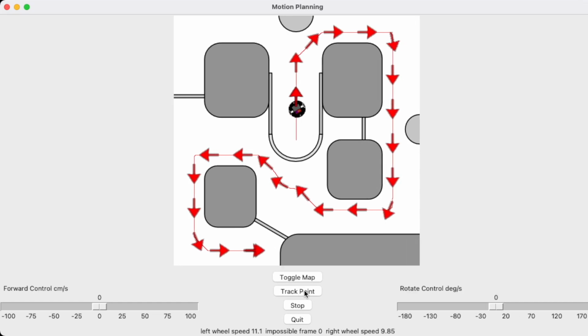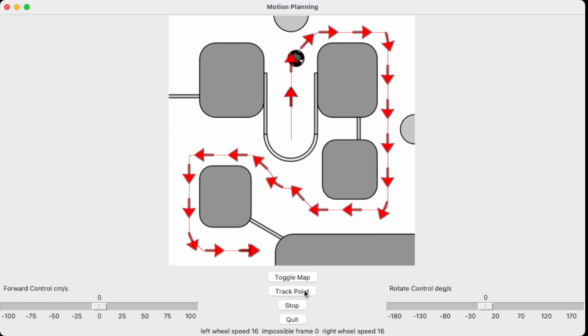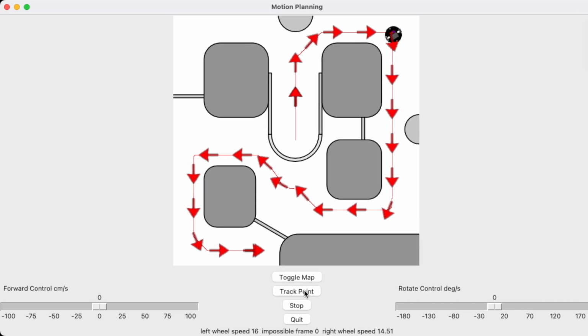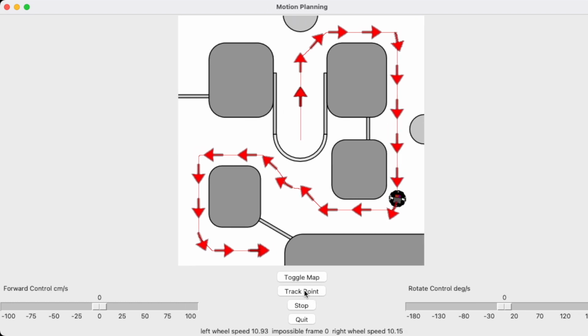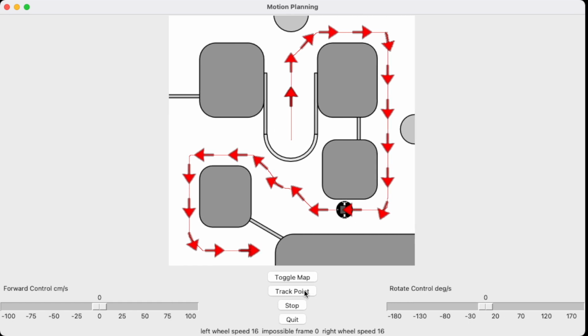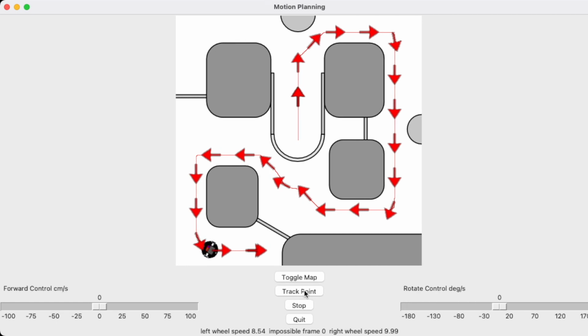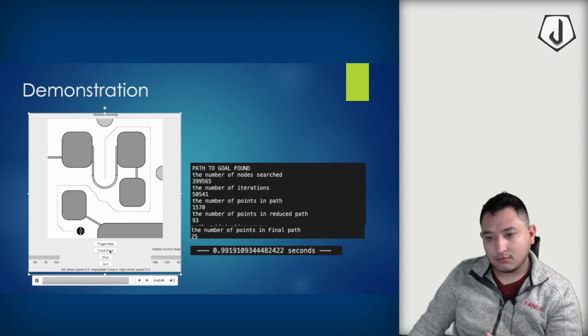As you can see, it moves very similar to a truck. It does not rotate in its place. It only takes curves along a maximum of 40 degrees steering angle. Its wheel velocity is limited to 20 rotations per second. As you can see, it will easily find its way from any starting position to any goal position as long as a valid path is there.